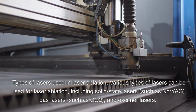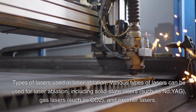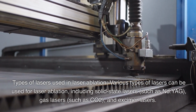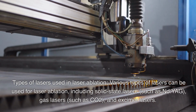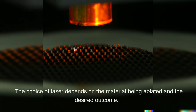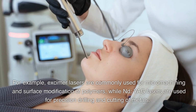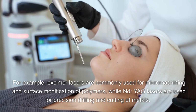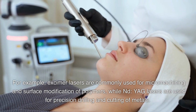Types of lasers used in laser ablation. Various types of lasers can be used for laser ablation, including solid-state lasers, such as ND-YAG, gas lasers, such as CO2, and excimer lasers. The choice of laser depends on the material being ablated and the desired outcome. For example, excimer lasers are commonly used for micromachining and surface modification of polymers, while ND-YAG lasers are used for precision drilling and cutting of metals.